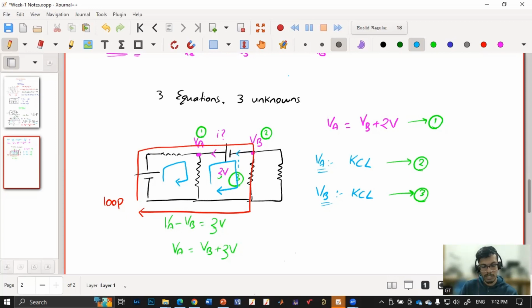But when we say mesh, within a mesh there should not exist another mesh. If I consider the outer loop as a mesh, inside it there are meshes, so it is not a mesh. To say it in an easy way, within a loop there can be another loop, but within a mesh there cannot be another mesh. Did it clarify your query, Yogita Jadhav? Yes, sir, everything clear.